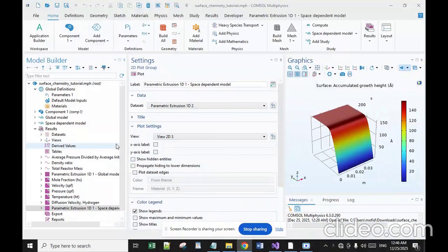Hot wall CVD, in which the chamber is heated by an external power source and the substrate is heated by radiation from the heated chamber walls. Cold wall CVD, in which only the substrate is directly heated, either by induction or by passing current through the substrate itself or a heater in contact with the substrate. The chamber walls are at room temperature. Plasma methods.